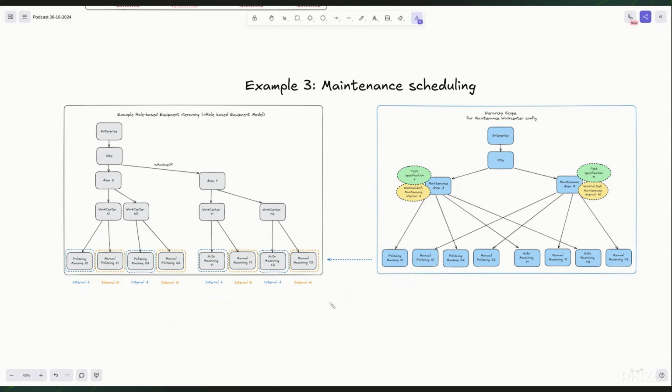So what that allows us to do is to say, okay, I've got my maintenance area 1, or maybe vendor A, that has its own set of work calendar definitions. So maybe a maintenance interval of every month that certain checks need to be done, or on a weekly basis. And on top of that, we can also have our test specifications. And in there, we can specify what kind of checks or what kind of maintenance we need to do. So maybe an example is measure the current of a motor, or some kind of pressure check.